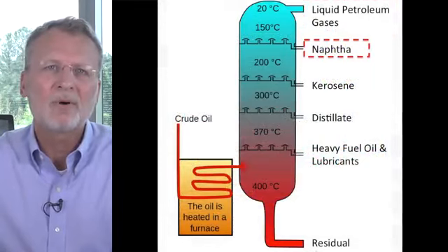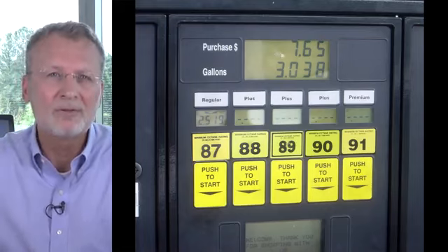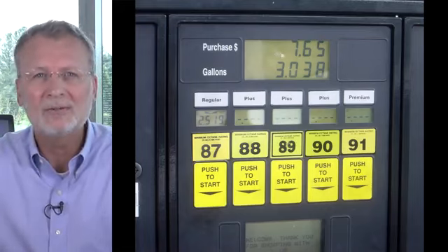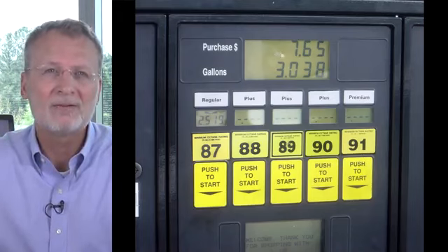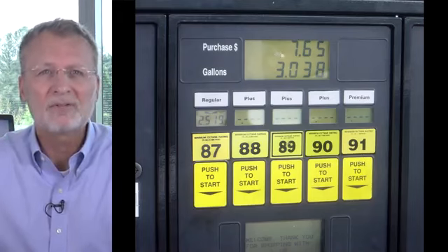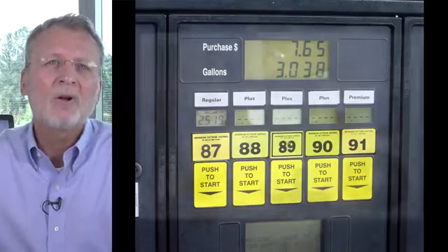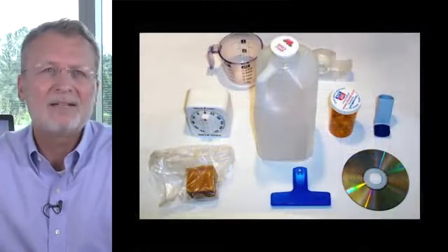These are hydrocarbon molecules containing 4 to 12 carbons. Naphthas are the principal feedstock for gasoline, the primary fuel used for transportation here in the U.S. Naphthas are also used to produce petrochemicals that in turn are used to create solvents, detergents, adhesives, pesticides, synthetic rubbers such as in tires, synthetic fabrics such as nylon and polyester, and all sorts of plastics from packing to containers and machine parts.